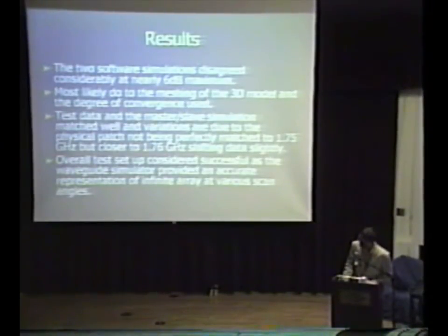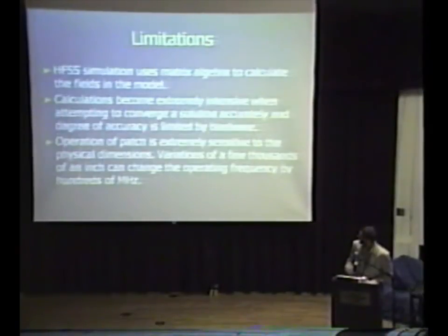Limitations on the project that I encountered were that the simulation software uses matrix algebra to calculate the fields. Calculations become extremely intensive and can take extremely large amounts of time if you want to get an accurate solution. Also, the operation of the patch is extremely sensitive to the physical dimensions. Variations of a few thousandths of an inch can change the operation frequency by hundreds of megahertz.